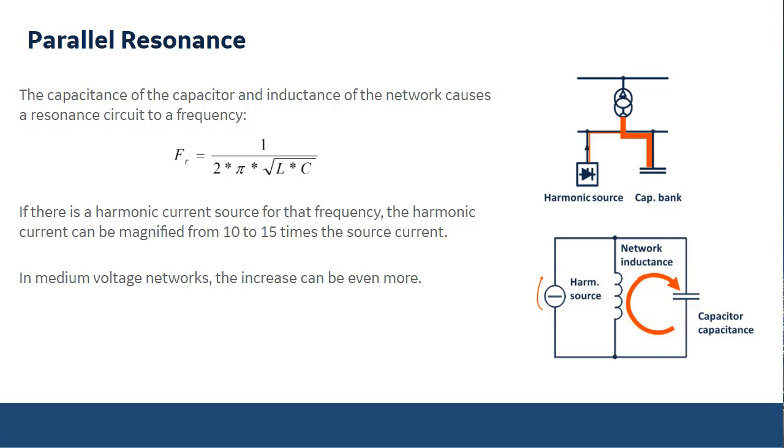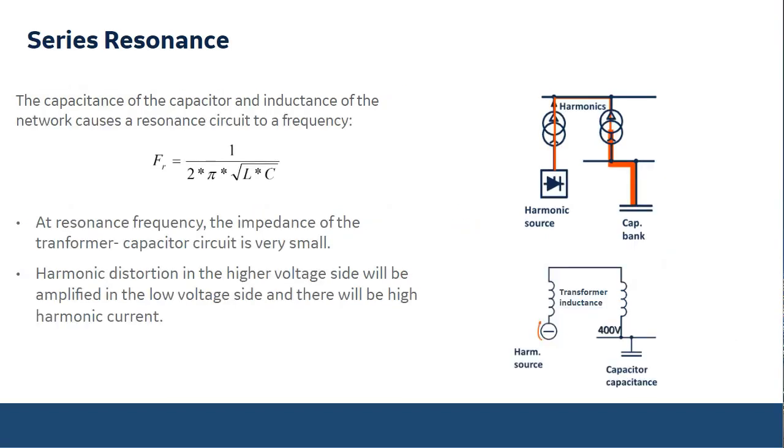Then the worst case is this serious resonance in here, because now the harmonic source is somewhere else and it's not the transformer what you have, or not in your network. It can be, for example, in a factory in a next spot or something like that. And then when they are doing their manufacturing there, if it's a factory, they will produce harmonics, and now it's injected there on the higher level.